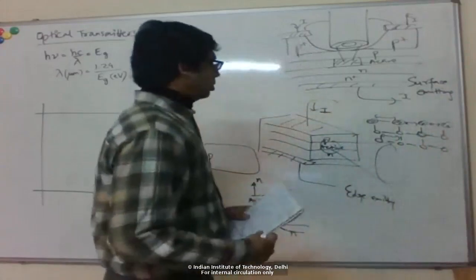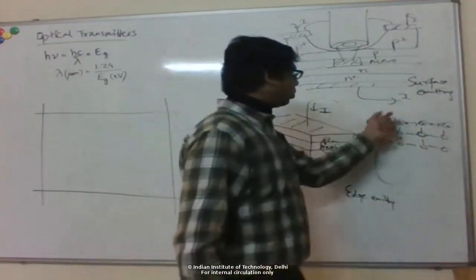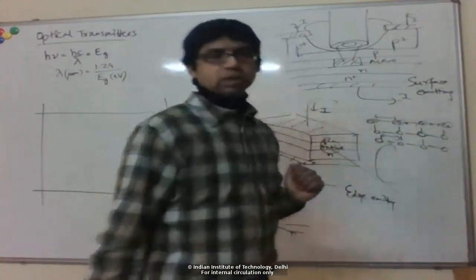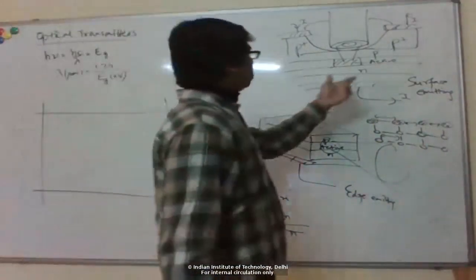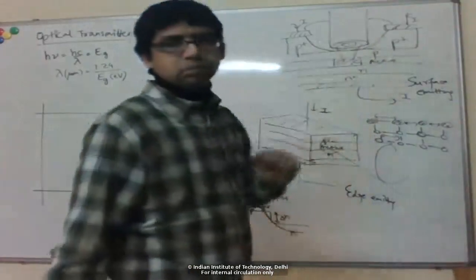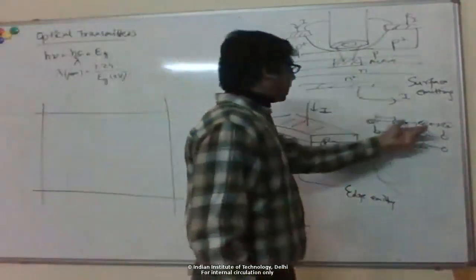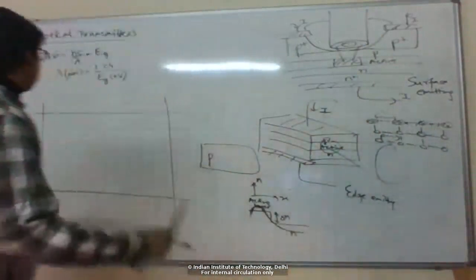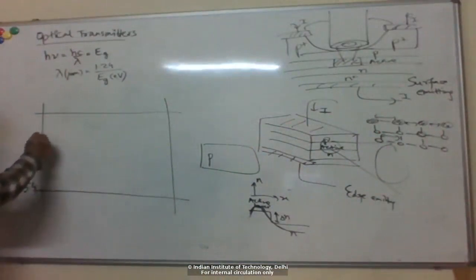These materials are grown by epitaxial growth, and you need to do what is known as lattice constant matching. You need to ensure that your N, active, and P regions have the same lattice constant, right? You want them to have different band gaps, but the lattice constant has to be the same. Fortunately, we can get this seemingly contradictory requirement